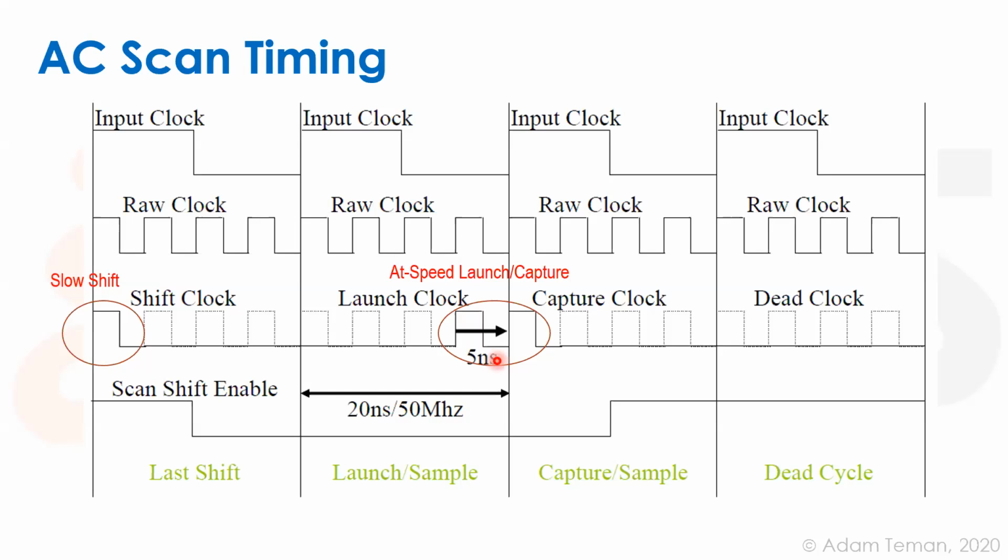There are ways to do it with 1 clock cycle, but from what I understand, they're not used at all. There are ways to do it with 3 clock cycles. But in any case, because it's not that simple 1 clock cycle, you actually need much more. You have a bigger controllability problem, and it's harder to get high coverage with at-speed testing. Plus, the problem with power consumption is even bigger.